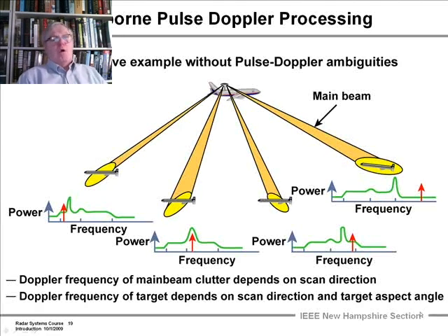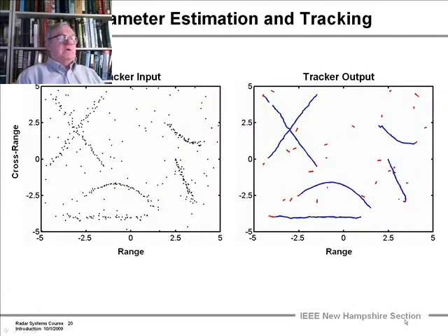We're going to go into this in a whole lecture. I went through it very quickly. Now, with those detections that we get, we want to correlate them. There may be several Doppler detections and several in range, and we consolidate them into one target, identifying them as having come in one scan of the radar from one individual object. That's parameter estimation and correlation: get the best value you know from that scan for the target. We're going to go into the parameter estimation issue in detail in a lecture.